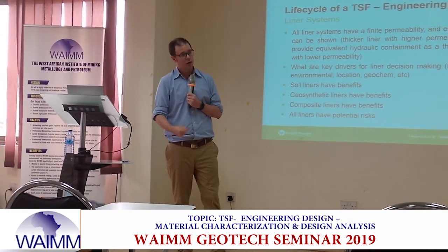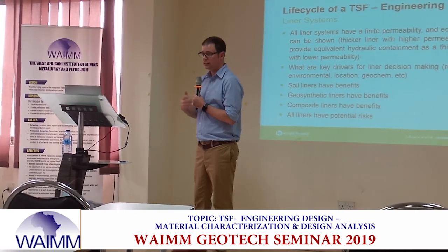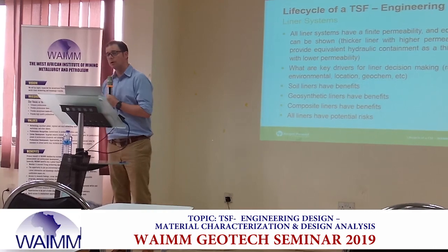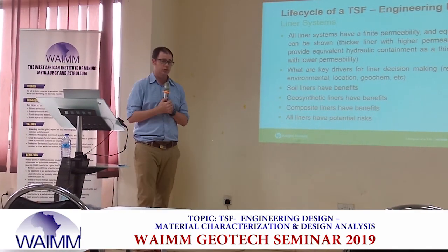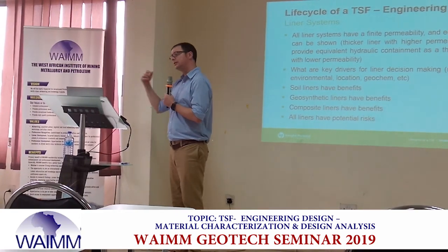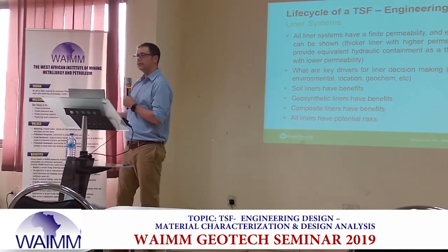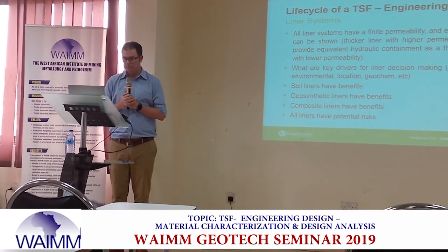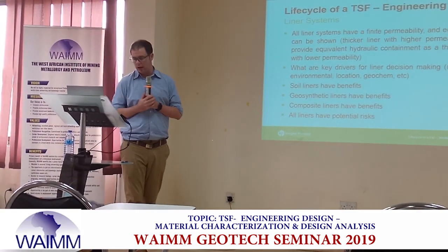Or LLDPE, or even PVC if it's still being used. Some of those may perform poorly when you start looking at chemical interaction. It might actually start breaking down the plastic where it does not negatively impact a natural material. Okay? All liners have benefits, all liners have risks.